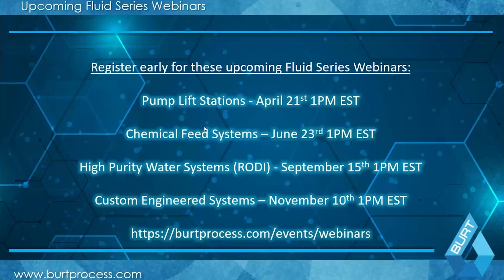If the waste stream is primarily neutral but contains a lot of high purity water, is buffering necessary? Yes and no. If your waste stream is primarily high purity water, probably the most important thing is to utilize a high purity water rated pH probe, especially if your waste doesn't really require much treatment. High purity water can leach the ions out of a lot of different pH probes, and that can lead to false readings in the system. So the first thing to check is to put in a high purity rated pH probe within your actual system.